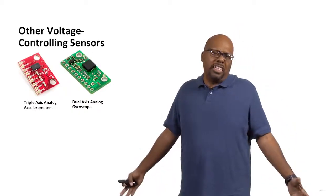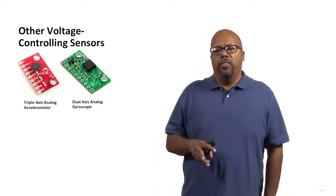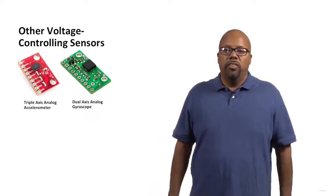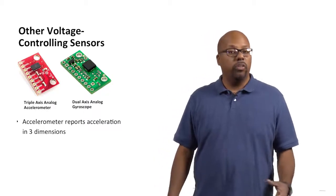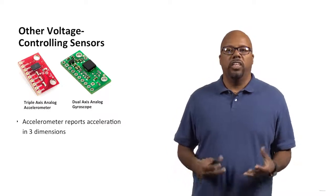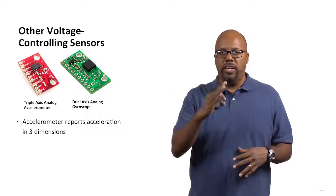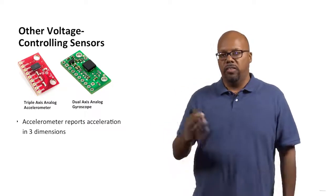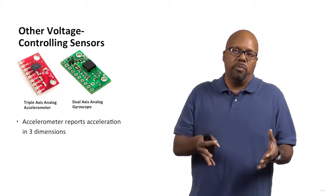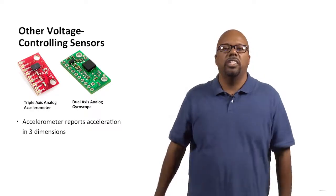Okay, so there are lots of different types of sensors that are voltage controlling, and here's a couple. The first one, the one over there on the left, is a triple axis analog accelerometer. So an accelerometer basically senses acceleration in 3 dimensions, so x, y, z. It'll tell you the acceleration. So this is useful for telling your orientation, right? Because there's always the acceleration of gravity. So you can tell the orientation of your device based on what this thing reports back, since you know what the gravitational acceleration is supposed to be.